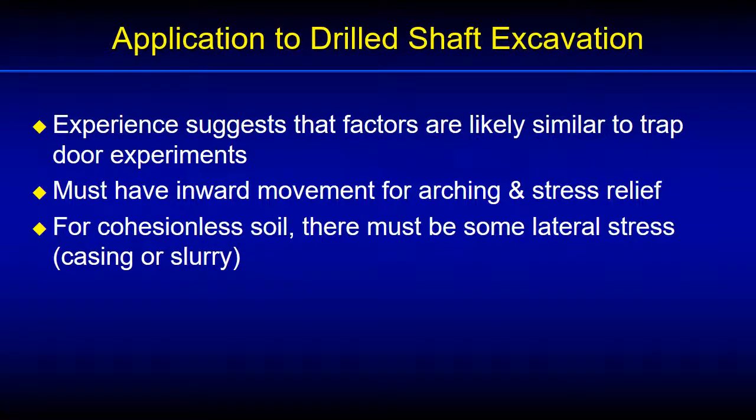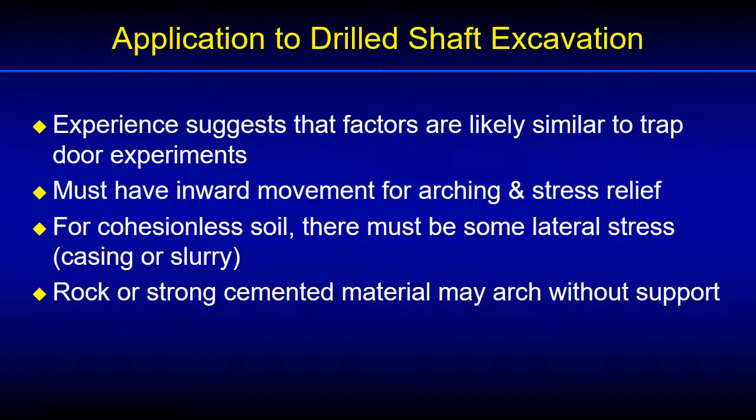Cemented materials such as rock may stand open for long periods of time without lateral restraining forces, just as a stone arch can be stable. Cohesive soil such as stiff clay may stand open for a short period, but we know there's a long-term tendency for clays to behave similarly to sands. So with our understanding of soil arching, we'll next look at drilled shaft construction techniques in more detail.